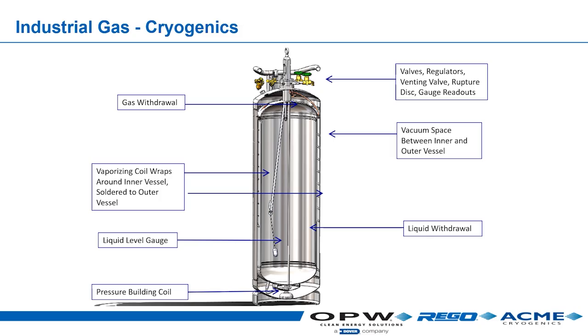On liquid cylinders, the space in between the outer and the inner goes back to the design. The more space you have, the worse that barrier is going to be. So they try to design it so it's very, very tight. And the challenge with nesting the inner vessel into the outer vessel is you can't scratch or tear any of that super insulation when you're nesting it, because if you do that, then that becomes a huge heat source.